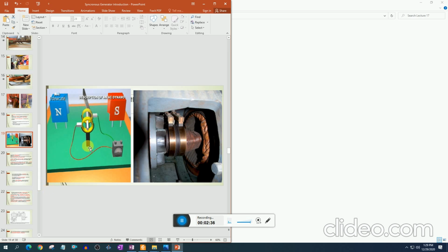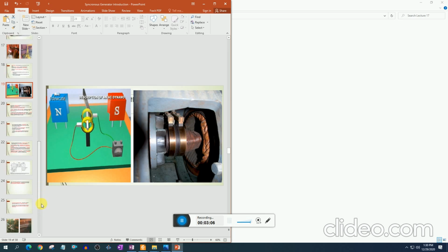In our power plant, every month we did this kind of maintenance and changed these brushes if required. Anyhow, in practical experience I saw that the brushes at the positive terminal are consumed more than the brushes on the negative terminal. So we swap them, putting the one already consumed on the negative side onto the positive side. In this way the life of these brushes increases.